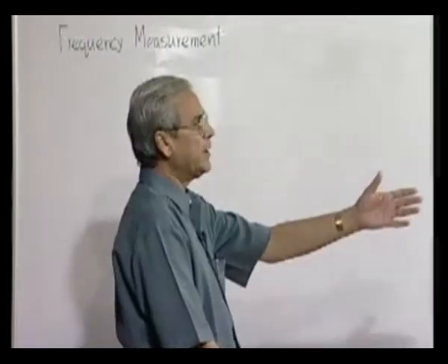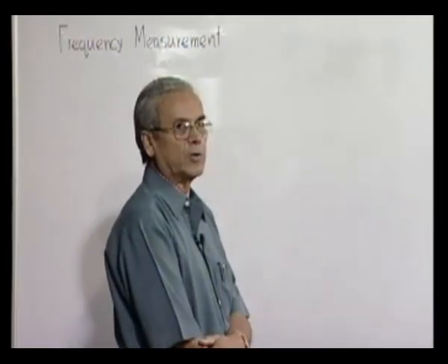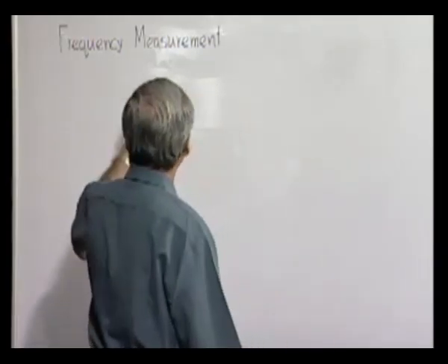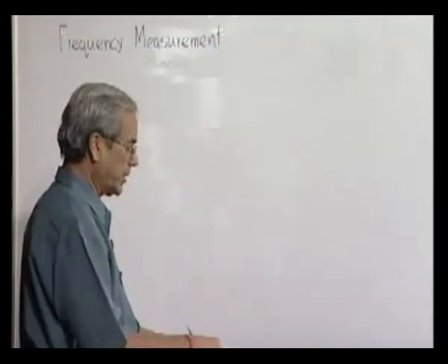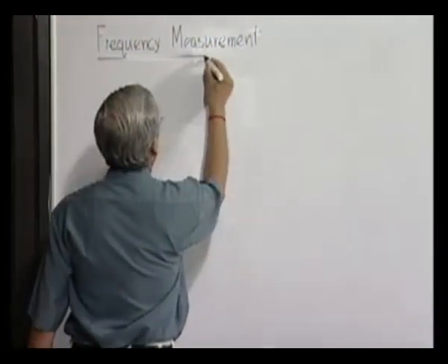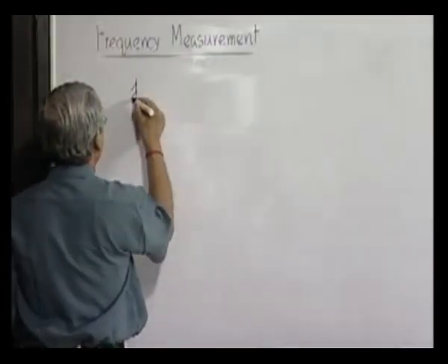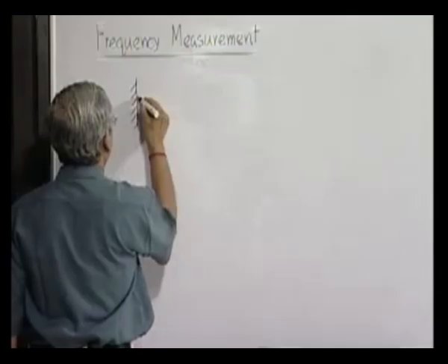But in a simple industrial scenario, quite often a mechanical vibration transducer we can utilize, which will give the frequency. The basic principle is the transverse vibration of a cantilever beam.